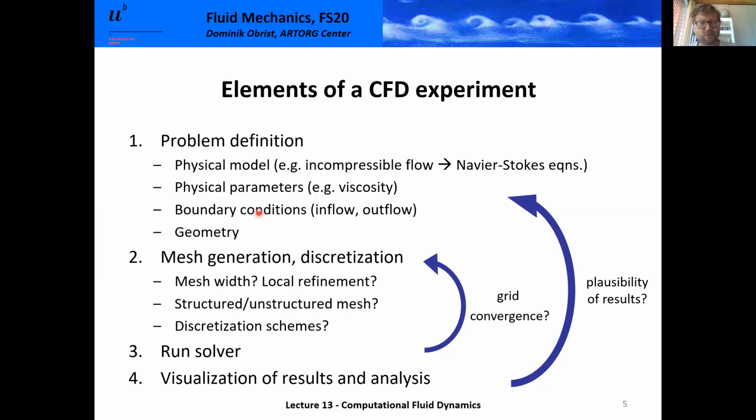Just the same way you also have these problems in the CFD code, because the computational domain, the domain in which you solve your flow, which contains maybe a wing, is of finite size. Although you're not really interested in what's happening at the boundaries of your computational domain, there are still boundaries.